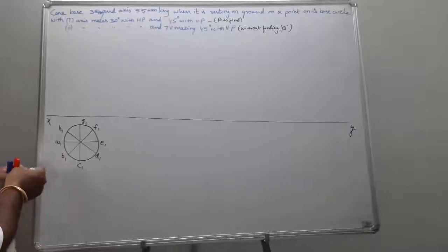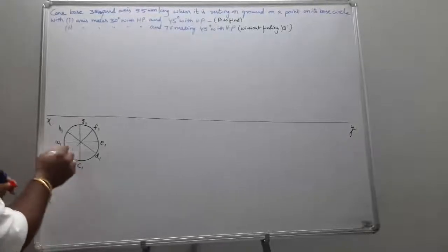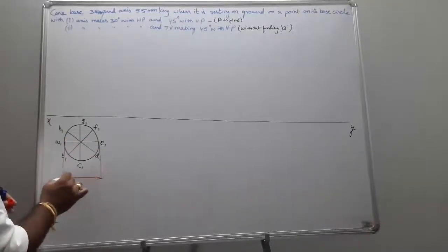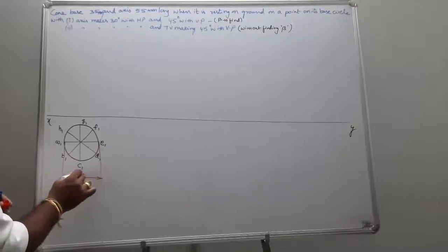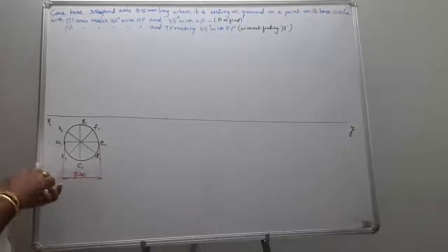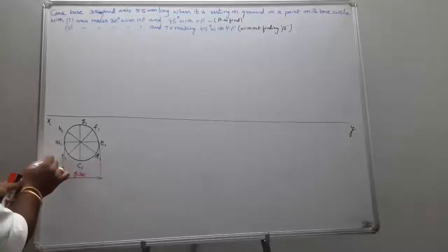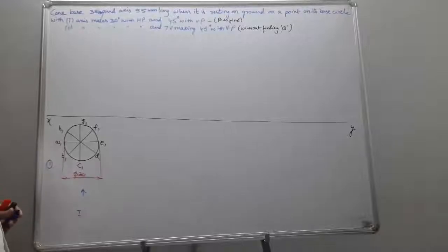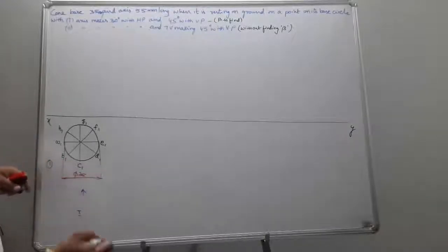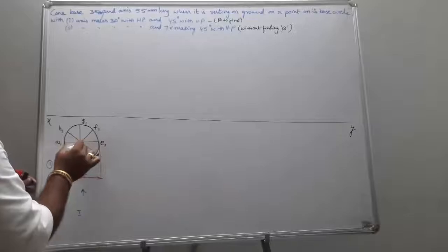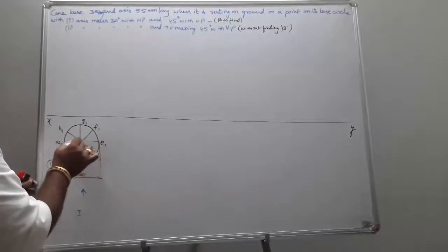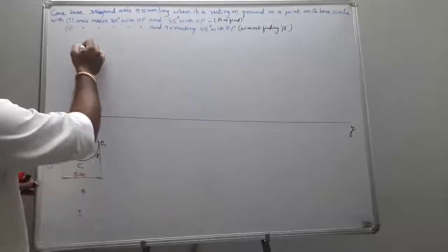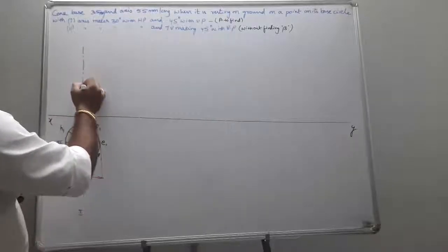What is the diameter? The diameter of the base is given as 35. And when your base is resting on HP, this becomes your first step, stage 1. Base is resting on HP means the front view comes on XY, the base is obtained on XY, and this becomes your O1 O2, the center. And the height of the axis is given as 55.